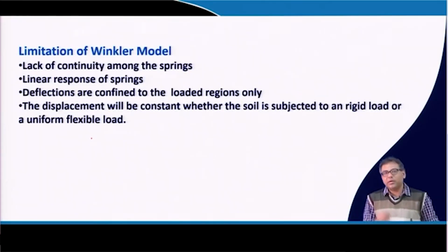Now, we are talking about the Winkler spring, Winkler model. So, the Winkler model has a few limitations. What are those limitations? One limitation is that there is no connectivity between the springs. But in an actual foundation, the soil is connected. That means once you apply a load on a foundation, it will deform, but the deformation will not be only in the loaded region.